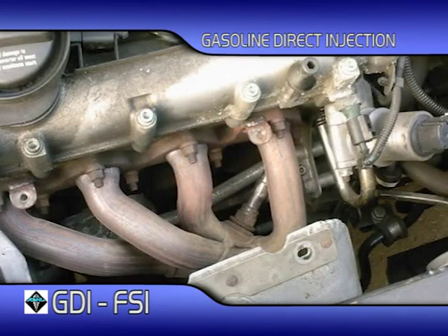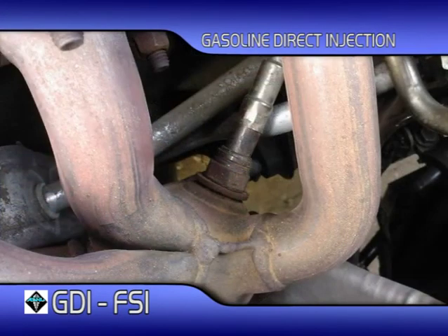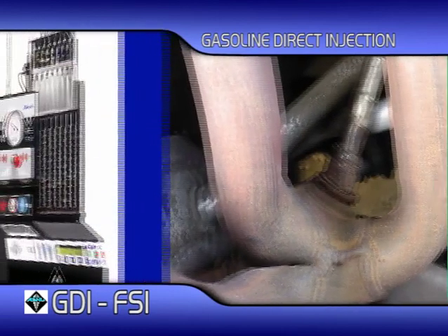The various sensors on the engine can identify even the slightest change in combustion. So, the need for high pressure testing is not as important as the correct supply of current to the injector.